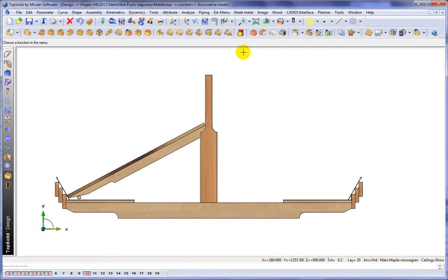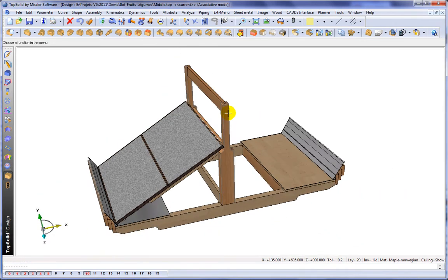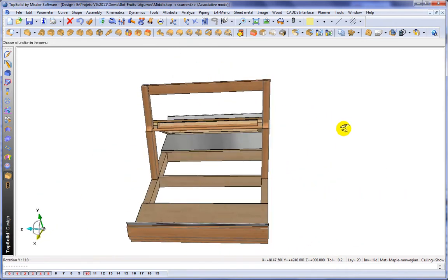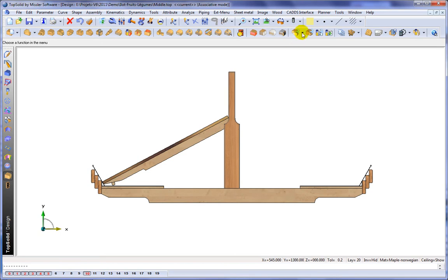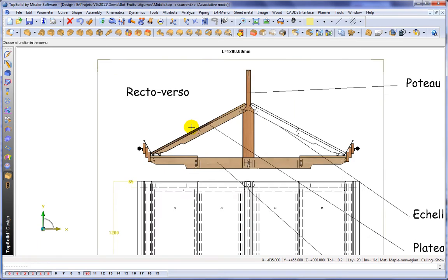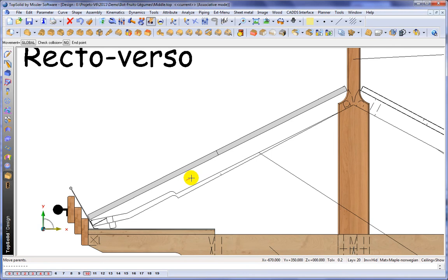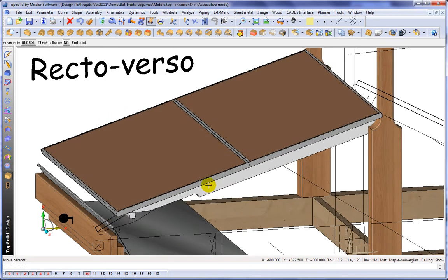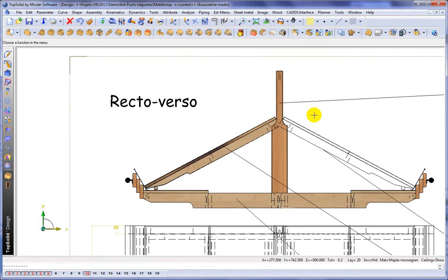Okay, so we've created in another design the roof section that attaches to this, and you can see that here. The reason we created it as another design is because this way we can test it in our assembly. So we have added that roof design to this design using a bottom-up assembly strategy. You can see it looks perfect. And moreover, we can test it. There's supposed to be a degree of freedom there, and there is. That's perfect. It's an advantage of using bottom-up assemblies.